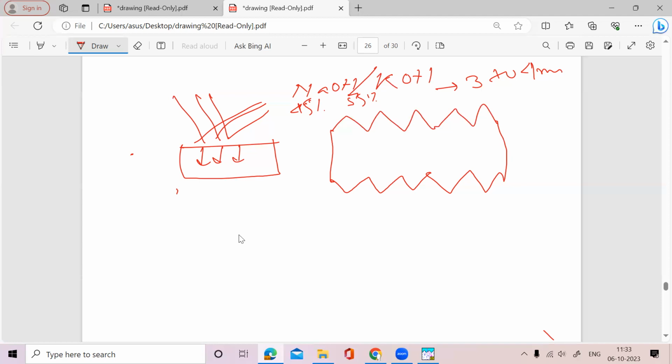Yes, it is called chemical etching or alkali etching. We are using alkali for etching. But one thing is there. You see that this is 54 degrees. The sharp point is 54. After this session you can try it with other angles also, and tell what result you find.